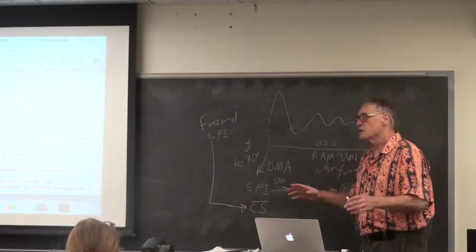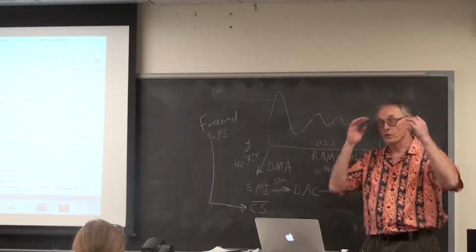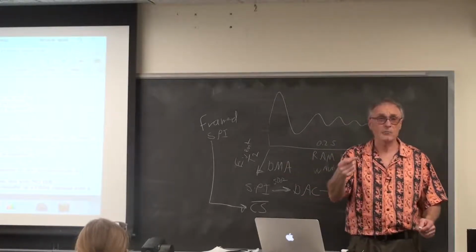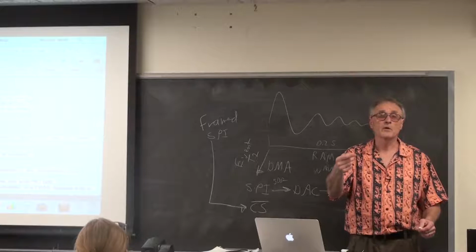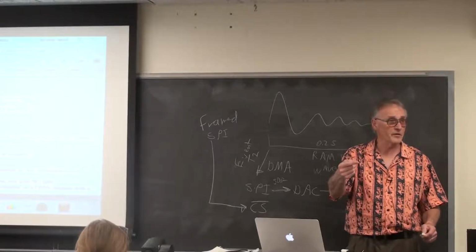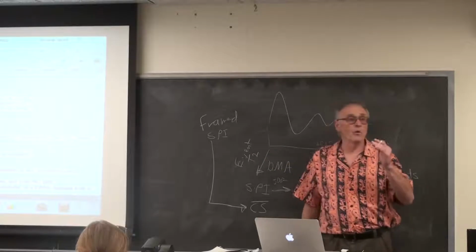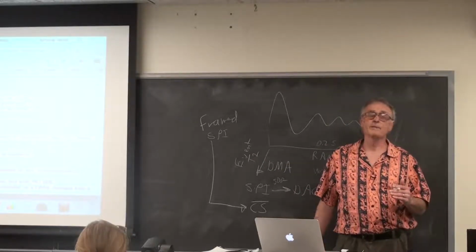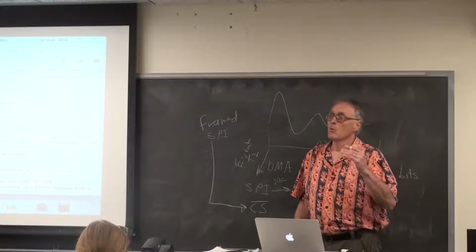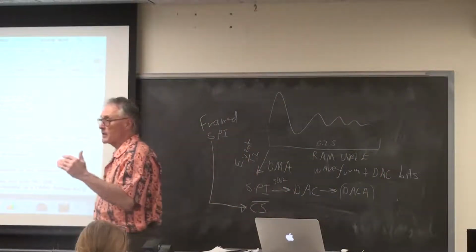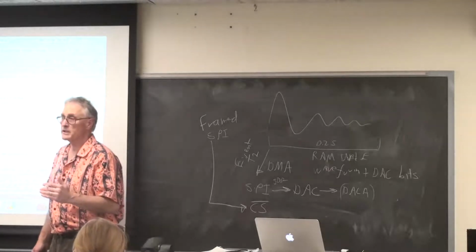So what you would do, what your thread would do, would be to enable a block transfer. The timer is going tick, tick, tick, tick, ticking away at that synthesis rate. Once you start the block transfer, you'll get multiple cell transfers until you reach the end of the table.